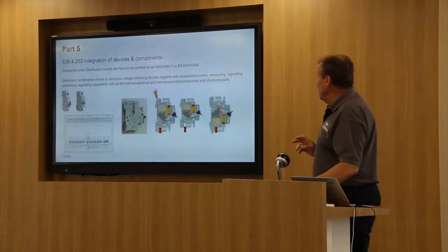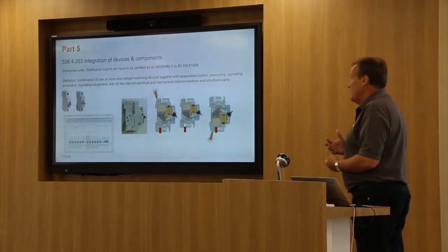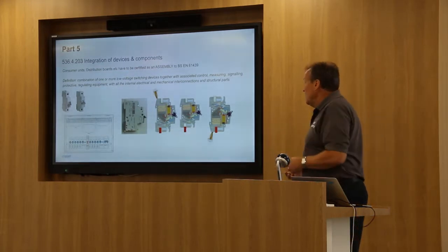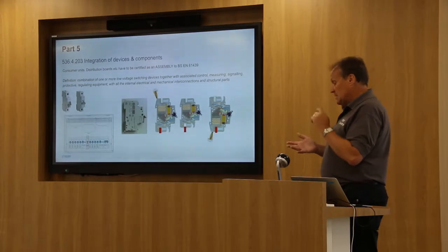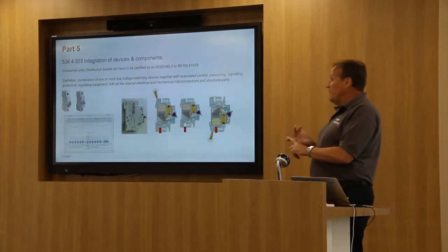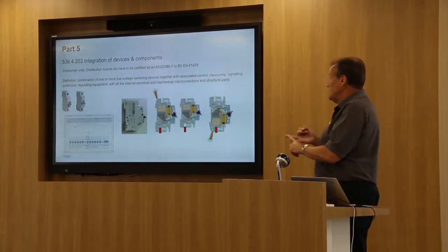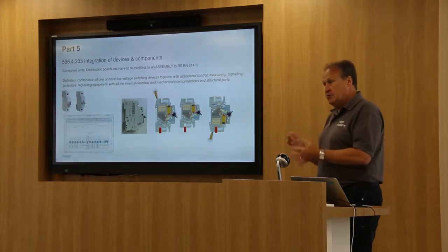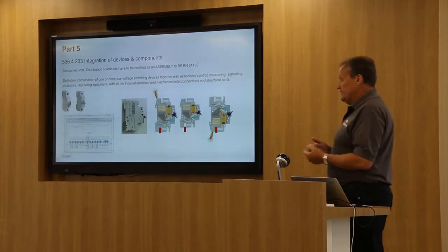Can you imagine another device which was organised differently put in there, and the gas was exhausted downwards below? Underneath the MCB is a busbar, and not too far away, of course, maybe a metal casing of the consumer unit at different voltages. You could quite easily generate a secondary explosion in that consumer unit.